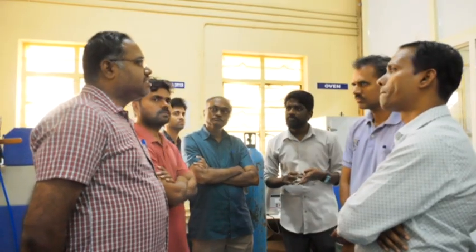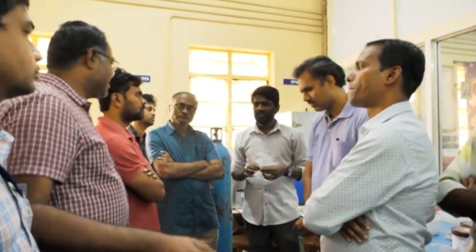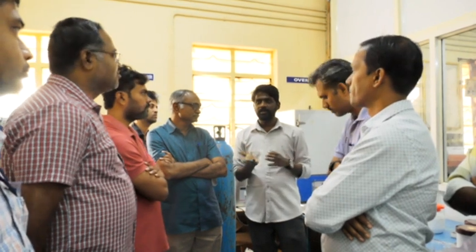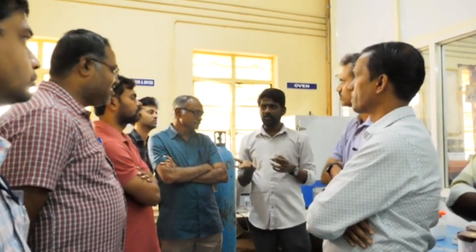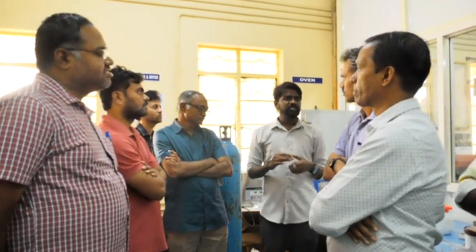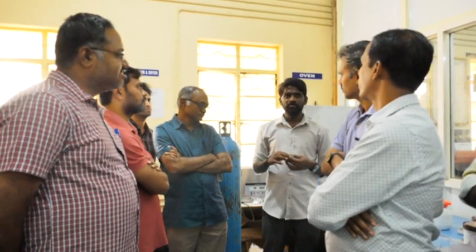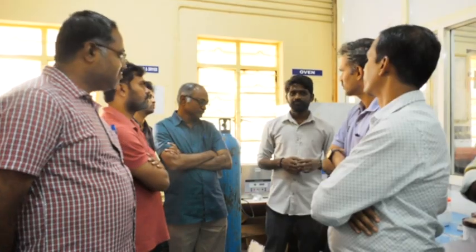Why? Because this grade 23 is a special alloy. Grade 5 you can easily get, but that is for industrial purposes, while grade 23 is for medical purposes, especially biomedical. It is having extra low interstitials, extra precision, less oxygen content mostly. And I think I printed some more lattice structures using the same grade 23 alloy. Right now we are in the development stage of the implant design, so we hope so.